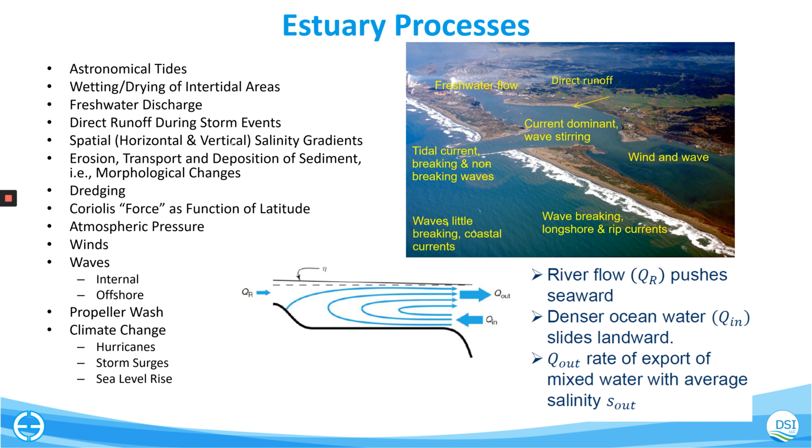Wind and waves, we're going to be dealing with the wave aspect of that a little bit later, but in most cases, wind is going to be a pretty important factor, especially in very slow moving estuaries, for inducing momentum into the water that can drive mixing. Tidal action, we're going to be discussing how you would use an open boundary condition today. That's pretty much the only way to set up a coastal model because usually you can't quantify the amount of flow in and out of an ocean boundary. It's just not something you can really measure.